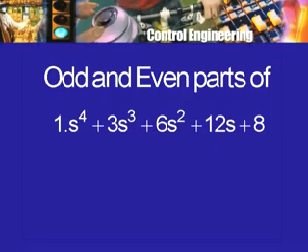So, in the Routh test or Routh array or table construction, what we are going to do is split the polynomial into its odd and even part. That is the first step, but we are going to do it in such a way that we will start constructing the table with this odd part and the even part.